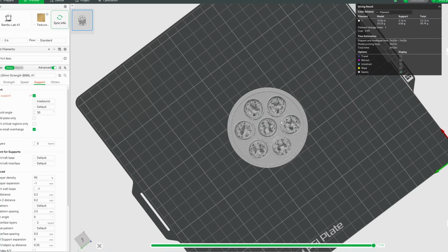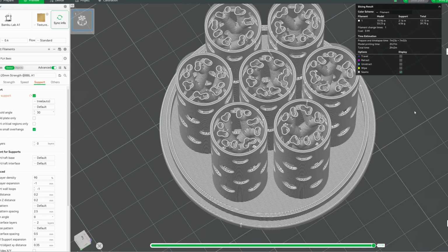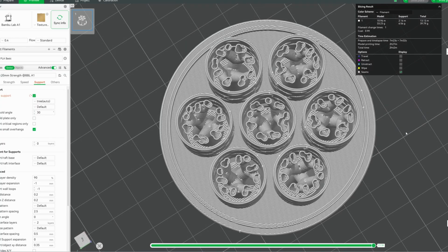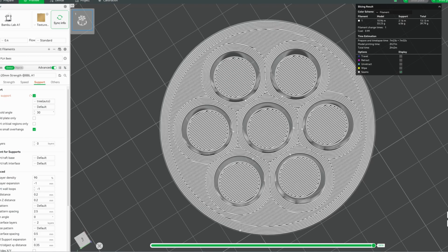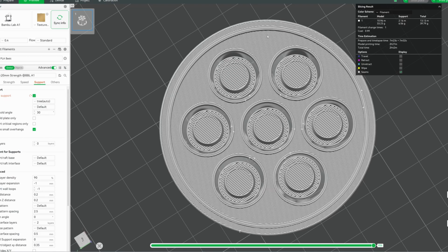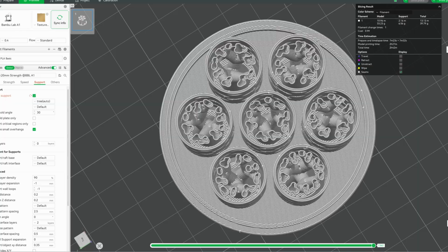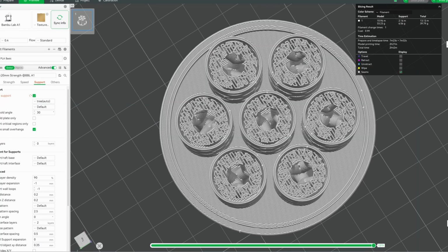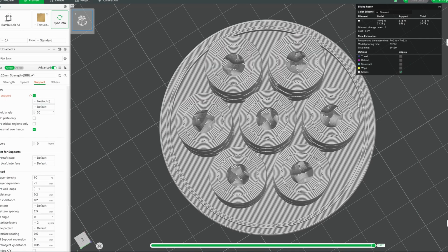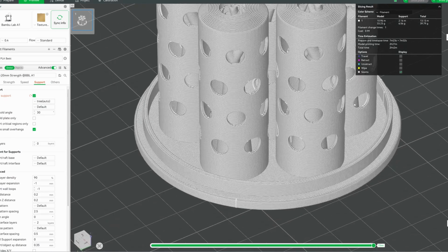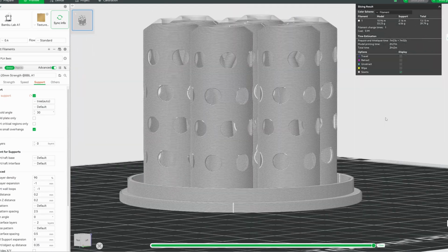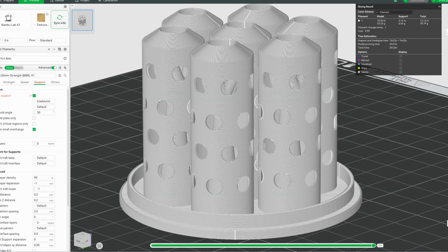You can start building from the inside. All this time that it's building is not really touching your design. This is your design. This is building inside. This is your support. But it's going to be crucial once you start getting at the very top, because it's going to be the support you need to start building this platform to make your bottom part. Right there, it builds.